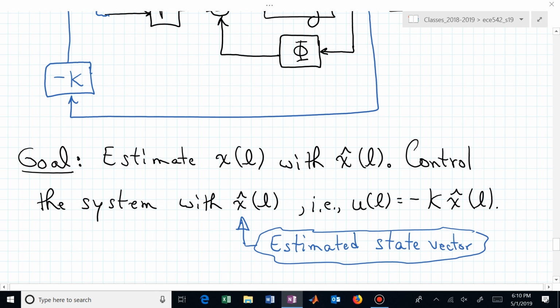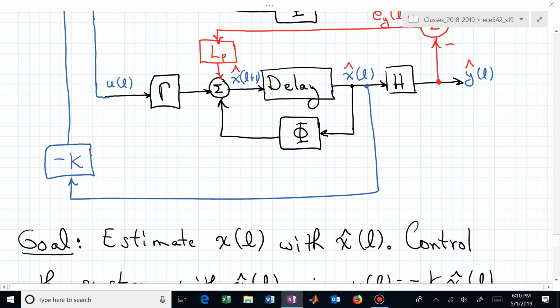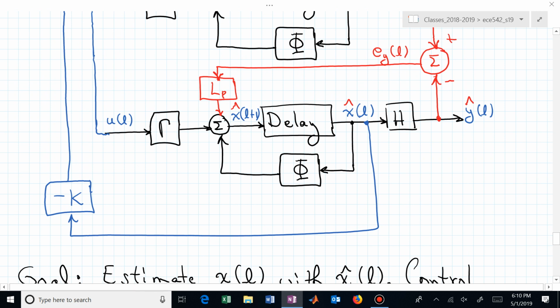But those are valid questions. But in this case, what I've given you so far, phi is exactly the same phi as our full dimensional system. And so it's a full order estimator, and so this is called a full order controller or full order compensator. Your compensator now will be 10th order. And you thought the PID was complicated. That's second order. Come on. So now if you had a 10th order system and you did a full order compensator, you would be automatically using a 10th order controller.